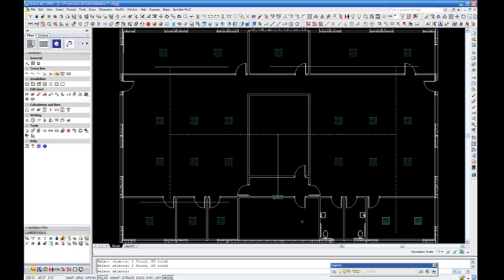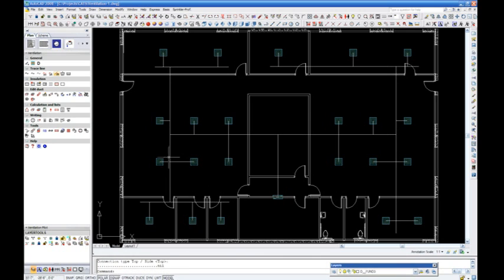Next, in the AutoCAD command, we are asked to select the trace line in which the diffusers will be connected. We are asked whether to connect the diffuser on the top or the side. We will select the top. And now all connections between the duct center line and the diffuser are completed. We are prompted to select the lines to be deleted. In the C.A.T.S commander, we select Automatic Duct Generation.